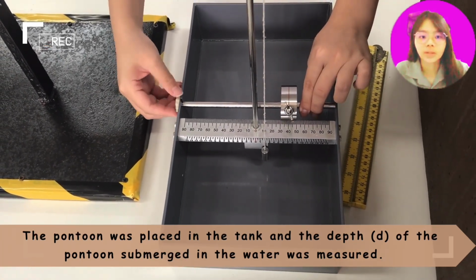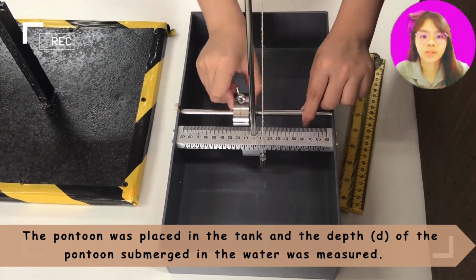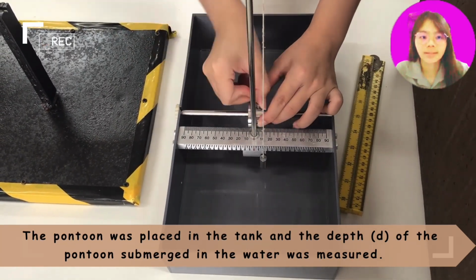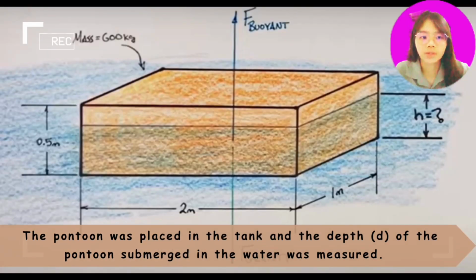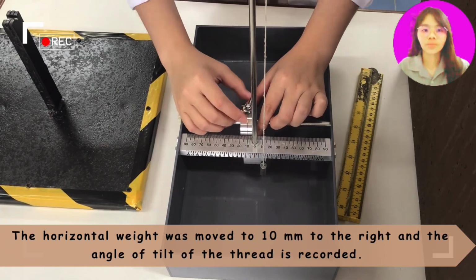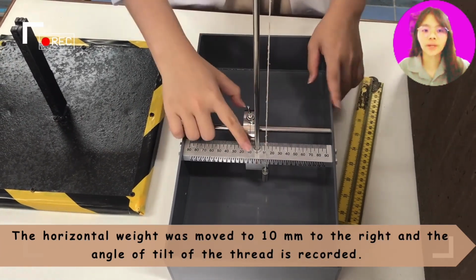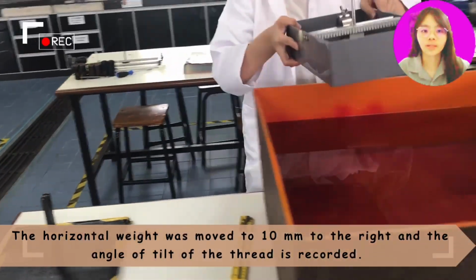Then the pontoon was placed in the tank and the depth of the pontoon submerged in the water was measured. This is an example picture for submerged depth measurement. Next, the horizontal weight was moved 10 mm to the right, and the angle of tilt of the thread is recorded when the string has stopped swinging.